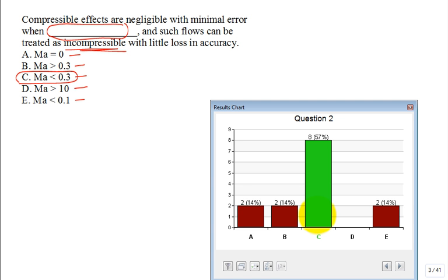Now, somebody will always ask about this. They'll say, hey, I've got an air compressor, and that air compressor takes air and squeezes it so the pressure ratio is maybe 10 to 1 or something. But it's not going fast through that air compressor. Can I treat the air as incompressible in my air compressor because the speed is never above 0.2 Mach inside the air compressor? Well, that's a whole different thing. I've got an air compressor changing the pressure by like 10 to 1 or something, 9 to 1. No, it's compressible, okay?